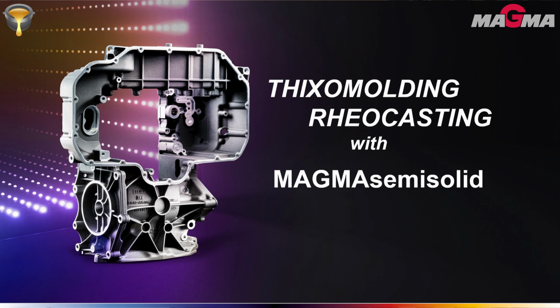We have a special model called Magma Semi-Solid. It's pretty easy, actually, where you can apply this special rheological flow behavior also in the virtual simulation. It has to be combined with special material data sets, again, because you need also special material data sets to describe the properties of the material. I would say we have the most commonly used alloys for aluminum and also magnesium we cover right now. I can reveal that it works just fine. Typical A356 casting.